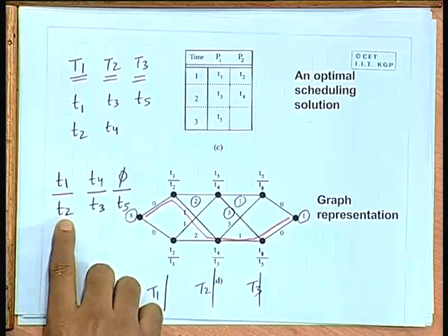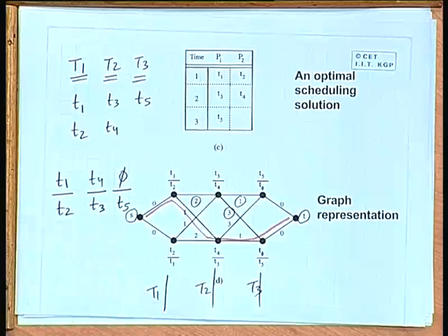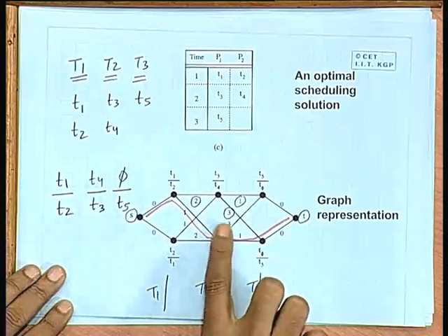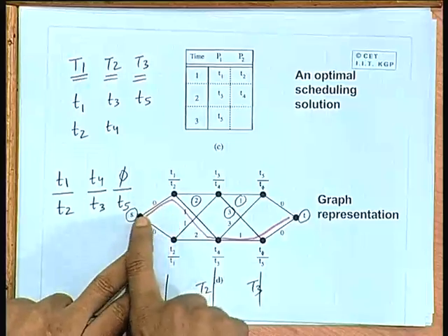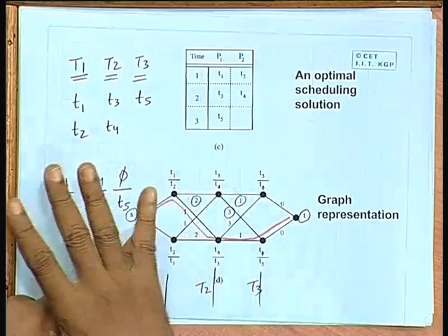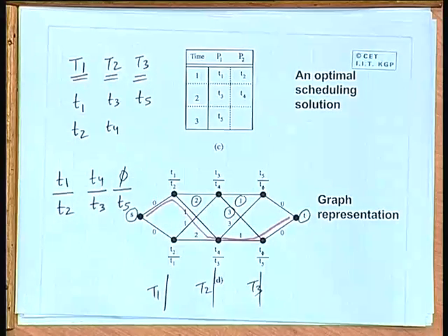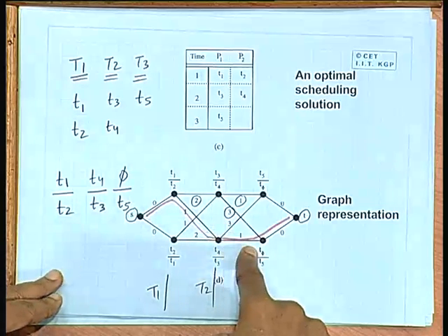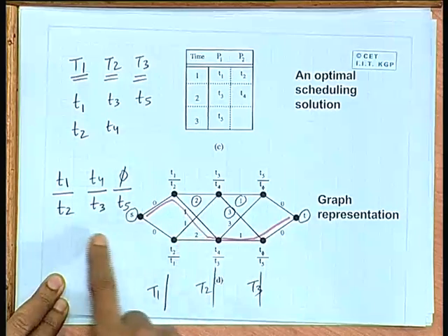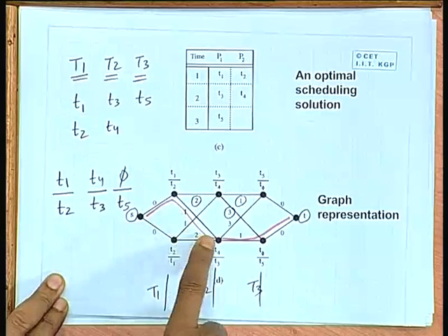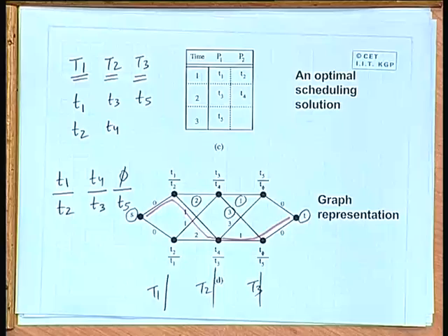So, if you assign the tracks in this way to the two layers, this graph helps in minimizing the number of via connections, because any path you select will be one feasible solution with the same number of tracks, 3, but the via connections may vary. So, if you find a minimum cost path in this graph, that will give you a solution with the minimum number of adjacent via connections. Okay. Fine.